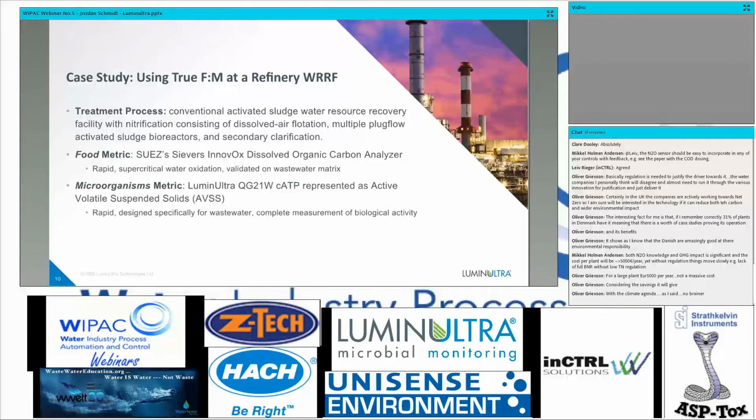For the food metric, we used a bit of an innovative technique with the Suez Sievers InnovOx dissolved organic carbon analyzer. They were a good partner of ours on this project, and a co-author on the magazine article as well. We really liked it. It's a rapid technique that uses supercritical water oxidation, so it's validated for a wastewater matrix, with no concerns about fouling over time.